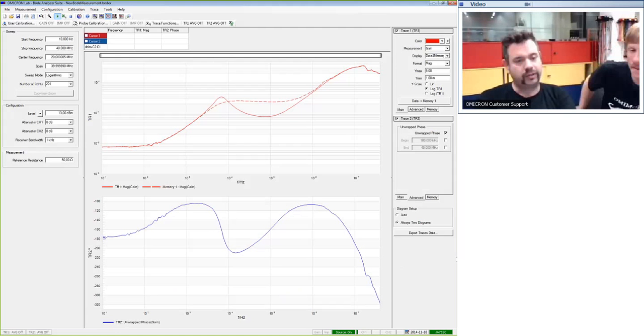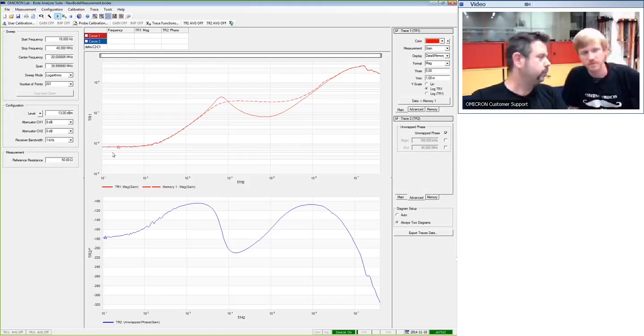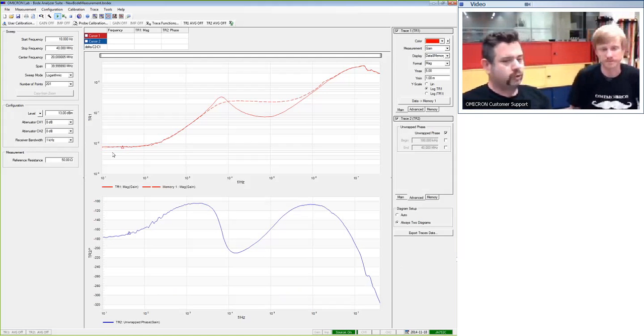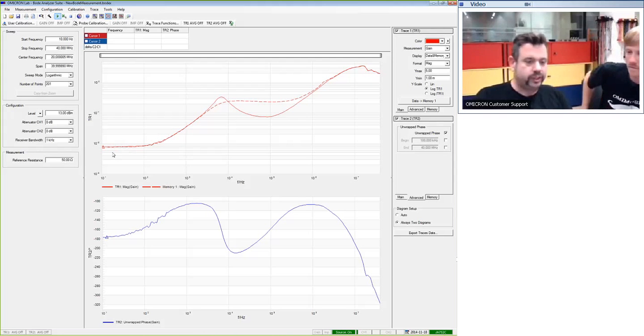Nevertheless, when we look at the curve, we see that we have a flat curve here in the beginning. So this means that our power supply is resistive. So what phase shift would you expect for a resistive behavior? Actually 0, and not minus 180. Yes, and we also had a look at this, and the reason why we are measuring minus 180 is because the injector is a current sink, so we are pulling out the current. If the current would go the opposite direction, we would have plus 180 degrees, and we would be at 0. So the only thing we need to know is that our new 0 is minus 180 degrees.